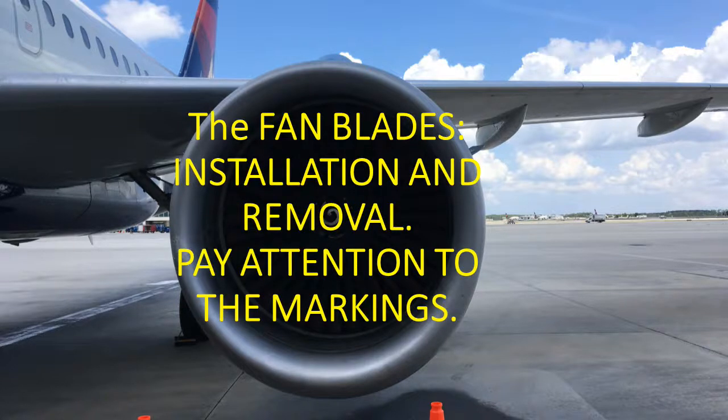Okay, and of course, be careful when you're installing and removing. They're marked. You can't just say, oh, this is a fan blade, they all look alike, let's just stick them here. You can't do that anyway, the way they're architecturally designed, and they're marked. So just be aware. Still, it's amazing how things can still happen, defying certain designs. Humans are humans, and things sometimes can be put the wrong way despite all the efforts to avoid that human error.